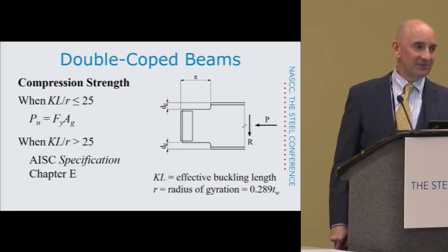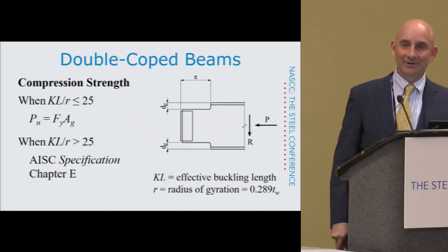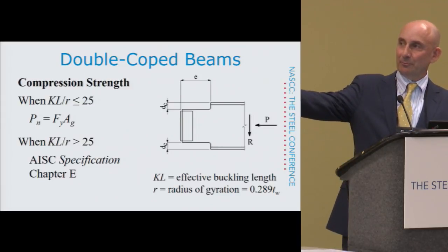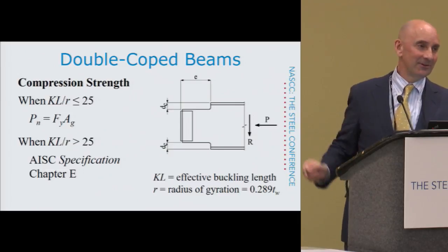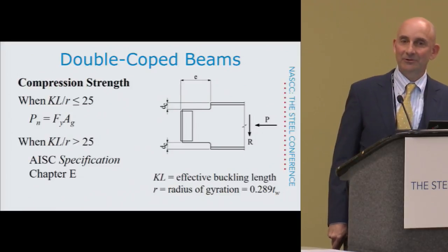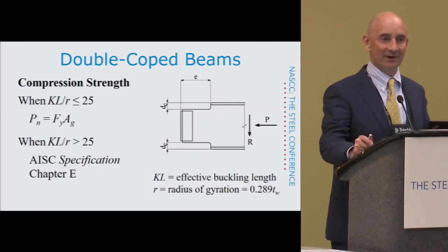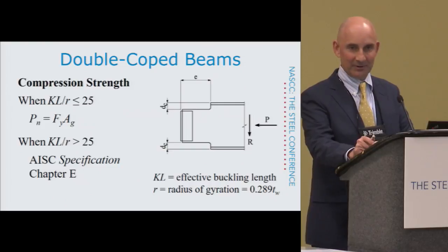But what if you have a jumbo shape with a 3.5-inch thick web and 3/8-inch thick clip angles, and that's not braced up here? Then I'm not sure what to use. I would assume no bending restraint here in that case. Using 3/8 clip angles, I don't think you could brace that web. So it's up to you to determine. If it's buckling in sway mode, you might want to think about using the sway buckling factors, the 1.2 or something like that, or maybe even 2.